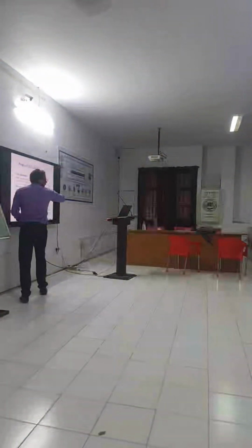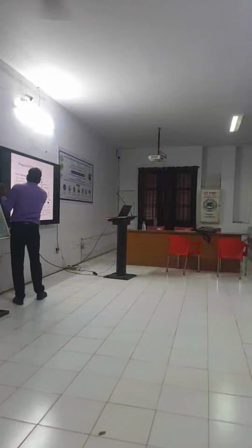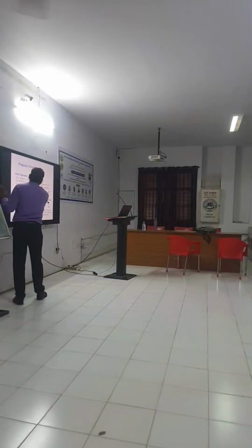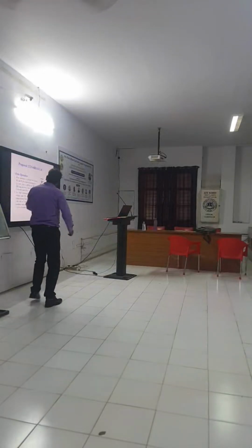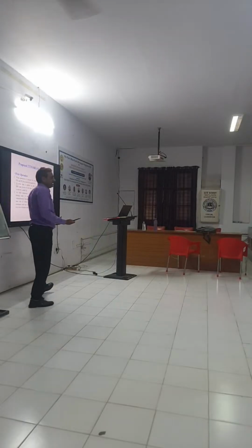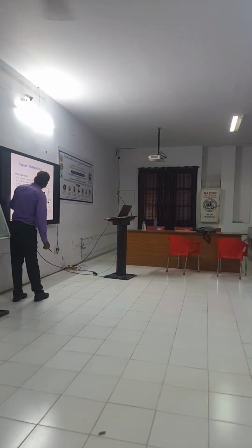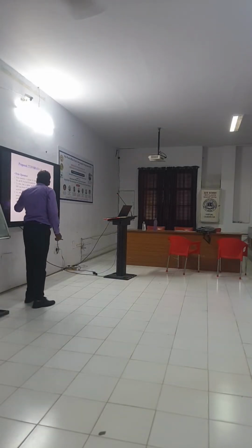This is just like a transmission gate, so strong 1 and strong 0 can pass. To write, data is applied to the data line. Whatever data you are going to write, suppose 0, then apply 0 here. Suppose you are writing 1, then apply 1 here. 1 means VDD, high. The data is applied to the data line, and the inverse of the data is applied to both BL and BLB.